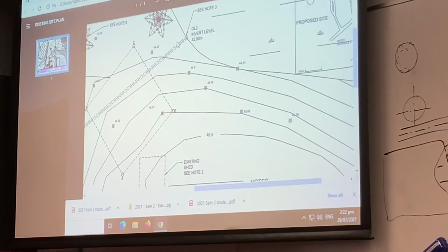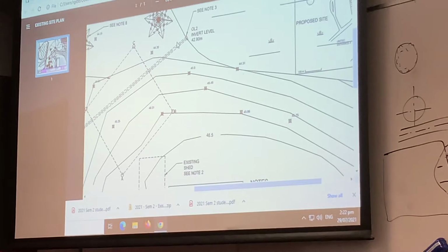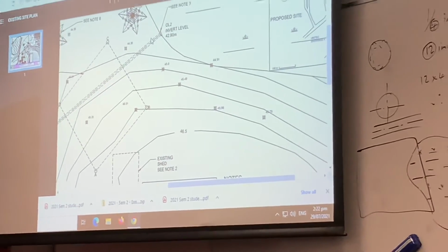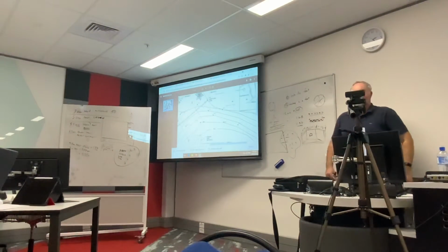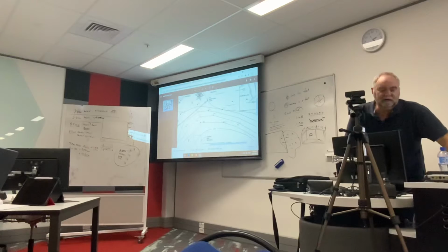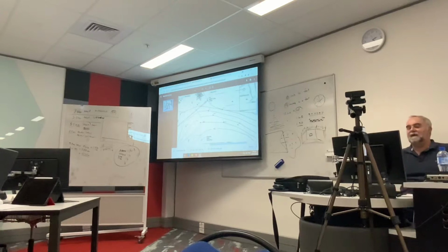The height of this is only going to be 100 mils above the ground level to stop the ground from coming over the top of the pipe. So ours will be fairly high. The standard ones come at different heights. I guess in engineering, in my time, I've always tried to do things with standard, so much easier. Standard trusses, standard outlet structures. If you can design around that, life's very easy, I can tell you that. And things go through council a lot easier.